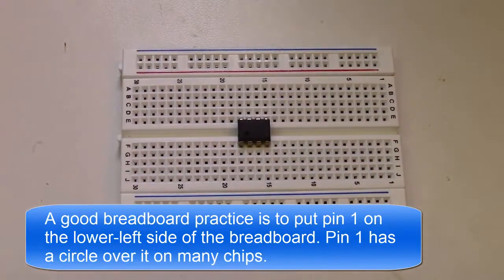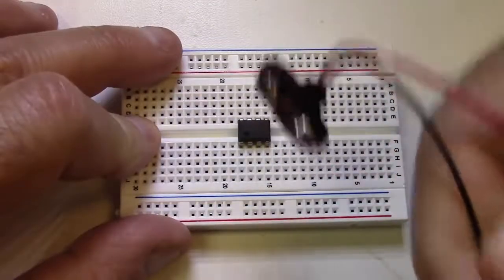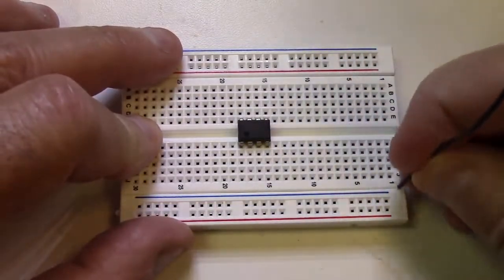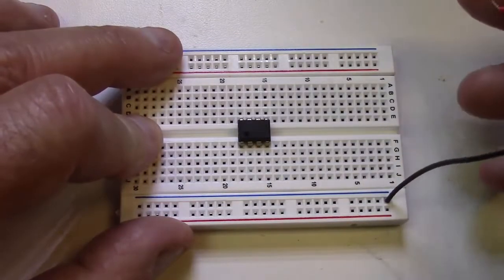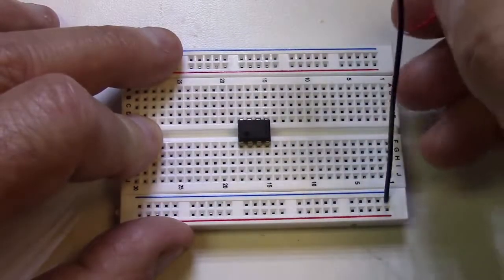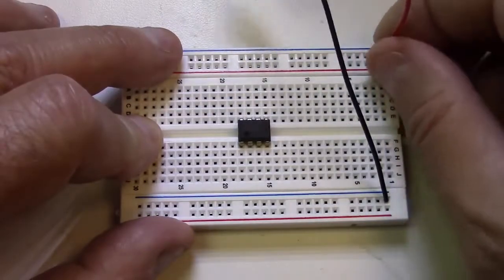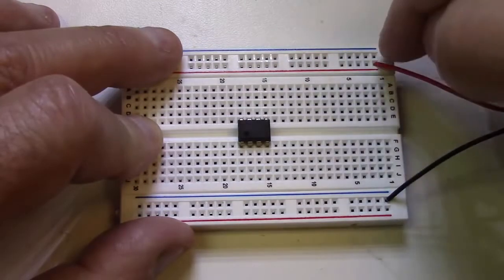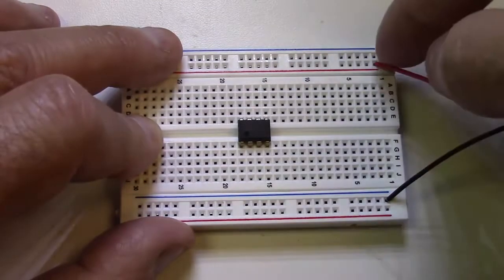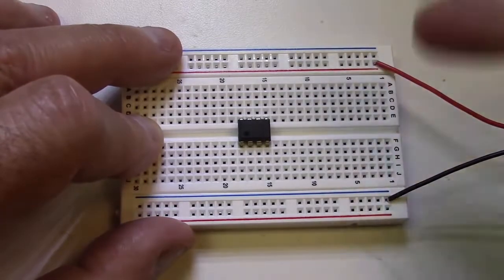And I like to put my power, and we're going to use a 9-volt battery clip here. I'm going to hook my ground to the blue bus on the bottom, and I'm going to hook my V plus to the red power bus on top of the breadboard. What I usually do is use a hot glue gun and glue these down when I'm using my breadboards. A lot of times I don't want these to pop up.